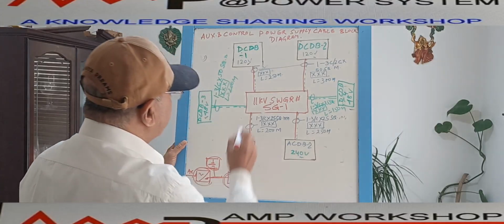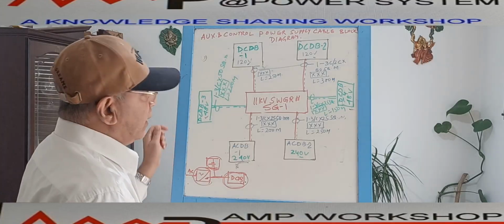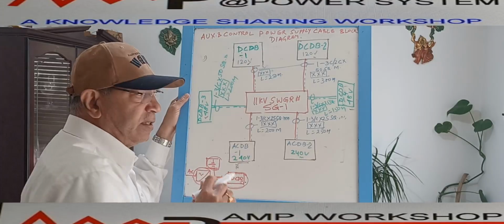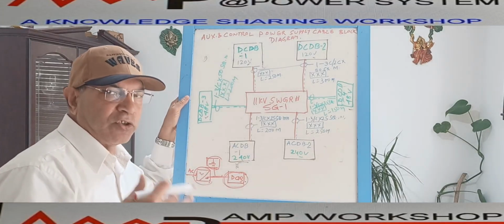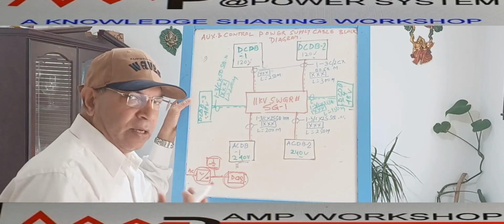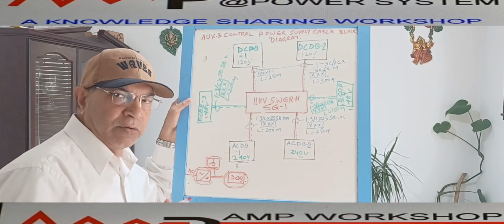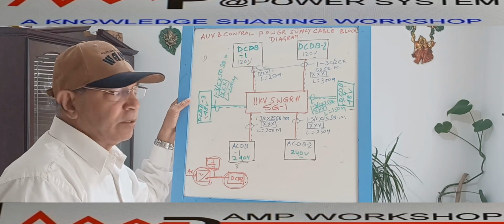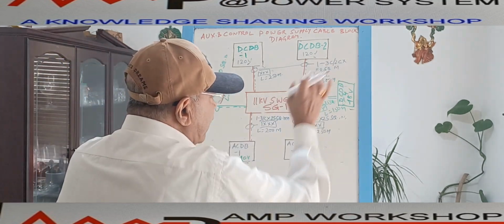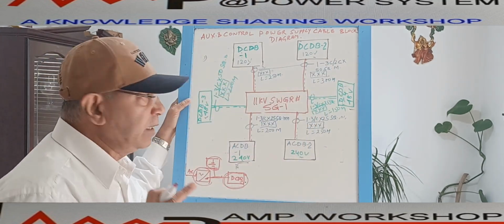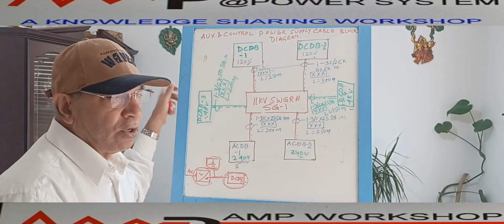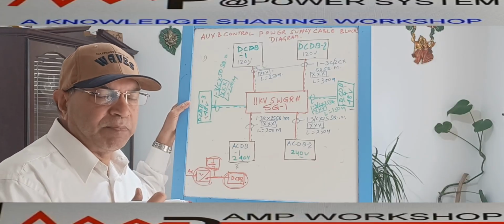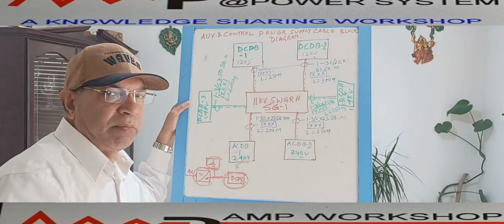So from this DCDB, this cable is coming. Now there are two cables. As DC has a positive and negative, or positive to ground, if the negative is grounded then positive to ground, or else positive to negative. But normally we lay a 3-core cable. This cable needs to be sized very precisely, because DC is not a very high voltage, 120 volt. If the voltage drop is more than 5%, then the various operations may be disturbed.